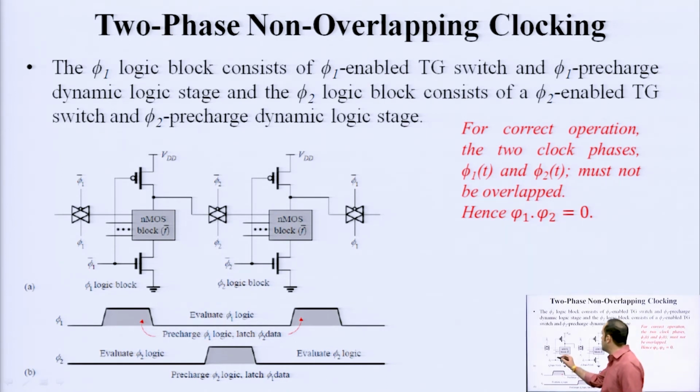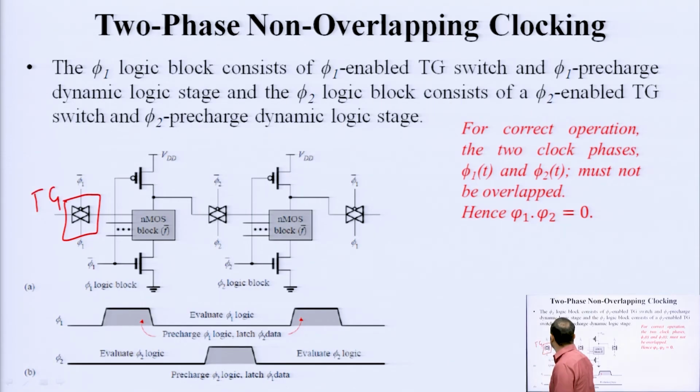This is the symbol of a transmission gate. So, this is a transmission gate. You can see there is a bubble here, which means this is your PMOS end, and there is no bubble here, this is your NMOS end. NMOS works on clock, PMOS works on clock complementary. If clock is 1, this works, in that case this goes to 0. So, this also works. When clock is 0, this is off and this is also off. So, this is like a switch, 0 or 1.